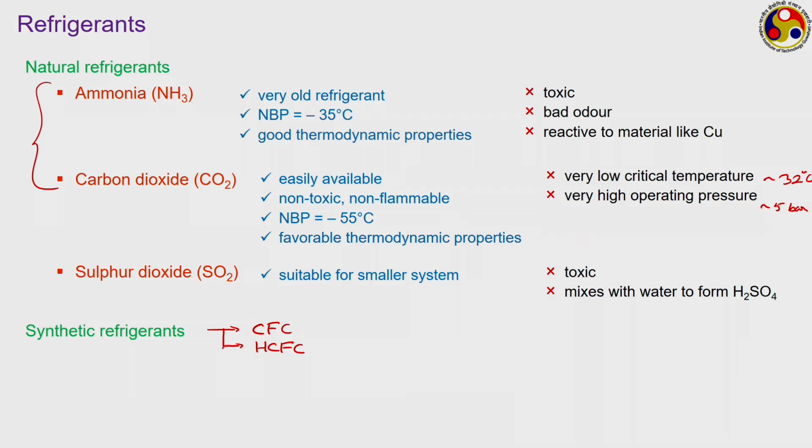So, it is HCFC, and finally, we can have HFC, where we do not have chlorine at all, it is hydrofluorocarbon. Hydrofluorocarbon talks about the complete removal of chlorine from the molecule, it is only hydrogen and fluorine along with carbon. So, these are synthetic refrigerants.